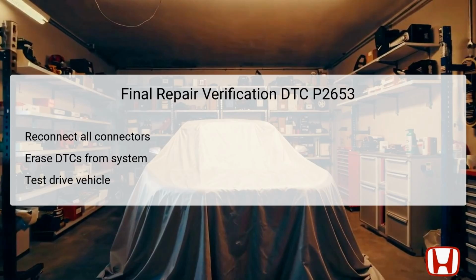After making the necessary repairs related to DTC P2653, it is essential to verify that the issue has been resolved. Begin by reconnecting all connectors that were previously disconnected during the troubleshooting process. Once reconnected, use the HDS to erase any DTCs from the system, ensuring a clean slate for ongoing diagnostics.